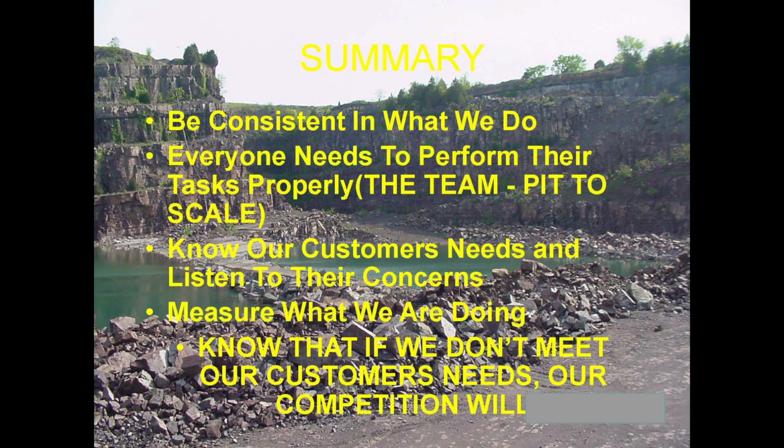Measure what you're doing. We do that in the plant all the time, right? We're constantly running gradations and doing adjustments, and we do process samples. We do quality control samples, so we check the stockpiles, we adjust our operation, our crushers, to make sure we're putting a consistent product out. And then we also check the material as it's been loaded on the truck to make sure that we don't have segregation issues going on there. And then we actually go out and take samples at our customers' yards and work together with them to make sure that they're not doing something that's creating segregation. Because again, it's a lot of handoffs, so we've got to pay attention to what our customers are doing and what their customers are doing. It keeps on going, right?